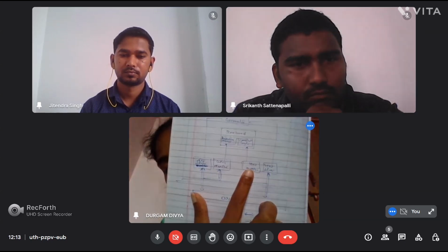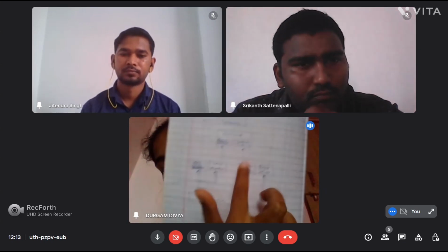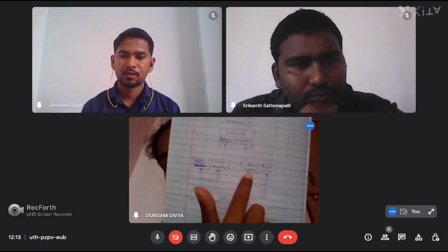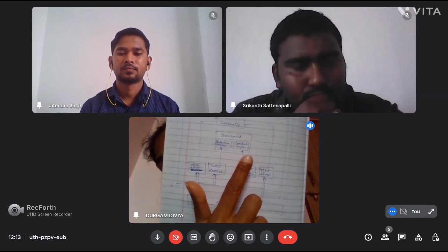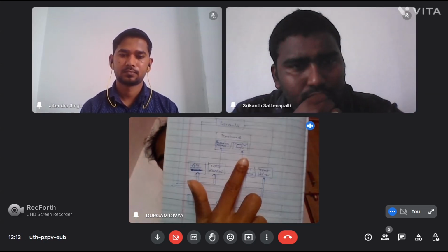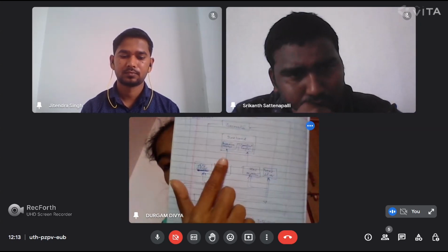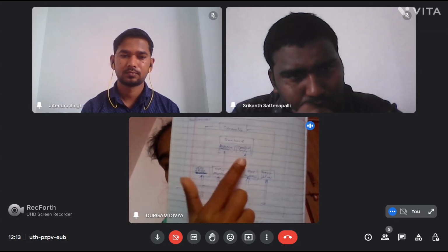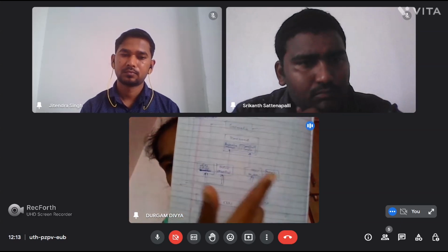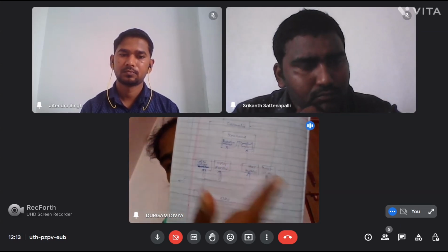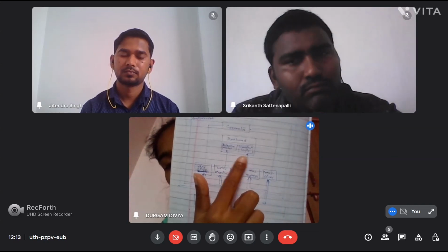When the monitor captures the digital format, it gives it to the reference model of the scoreboard. Whatever comes from the write driver or write monitor is taken as the reference output. The function of the scoreboard is to compare the reference output to the expected output and give the appropriate output for whatever design or project we are doing.